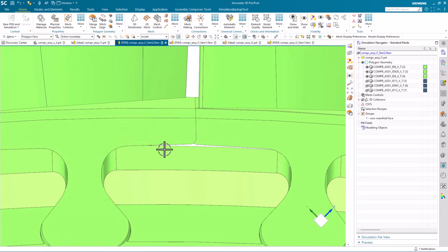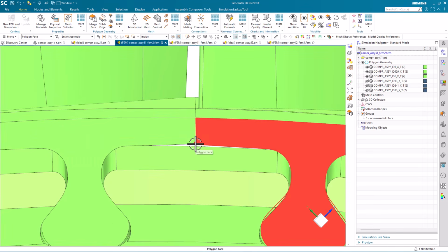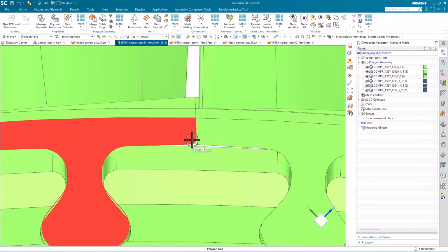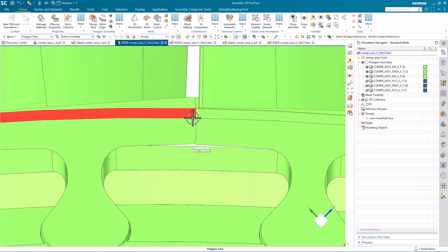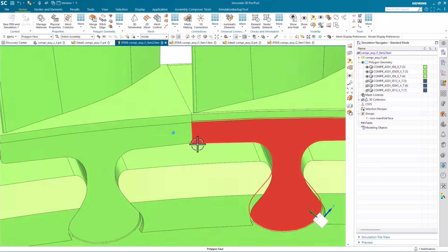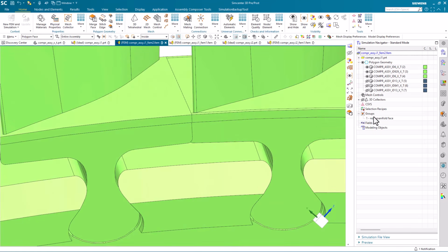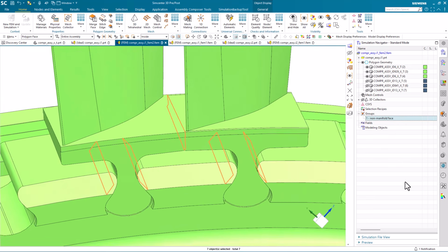You can see this body has its full representation, and then the body on the right has been trimmed off in a subtract body kind of way, so that the intersection that was this little bit up here is actually retained on this body and removed from that one, and then we retain our boundary via that non-manifold surface.